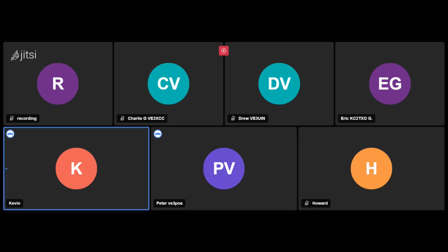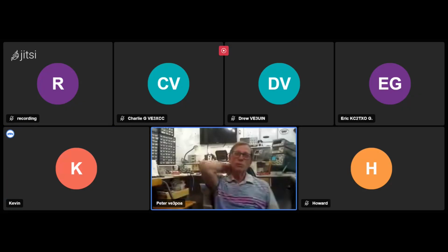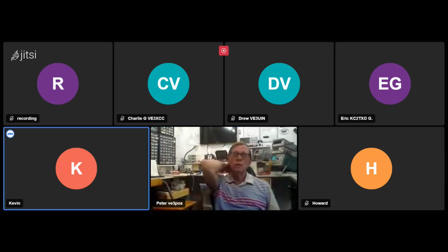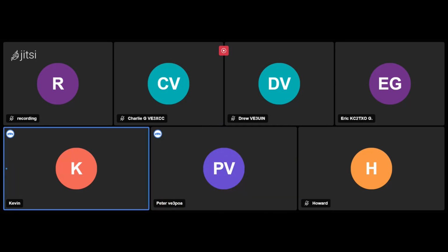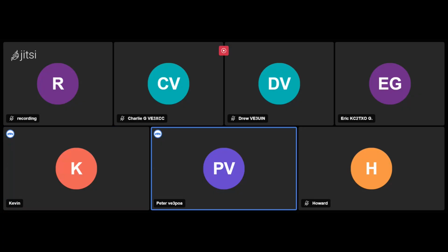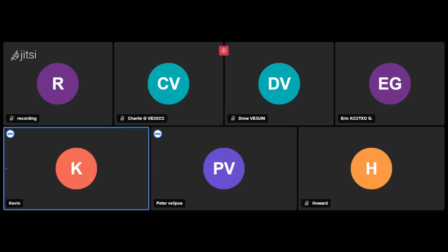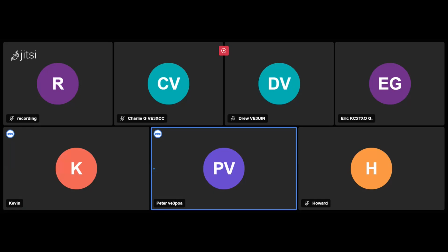But how many hertz per bin? I'm not sure what the division was. It looked like it was fine enough to be useful. Okay, well, even if you had like 128 there, that's still 8.3, that's still 20-some hertz per bin. That's still useful. That's okay. Yeah, because that cuts down the amount of math, right? Well, it depends on what you want. This is a start to see what it does, and then if you decide you want to go further, now you've got to change out the Arduino to something else.